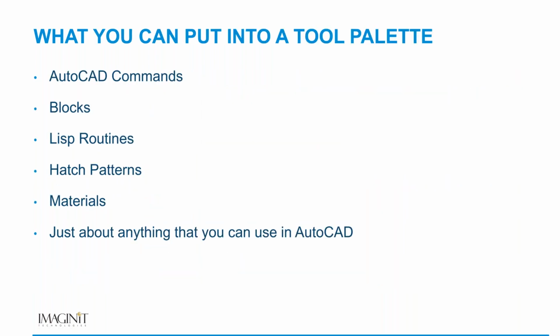So what can you put into a tool palette? Well, pretty much anything. You can put AutoCAD commands, you can put blocks, and you're not actually putting a block in there, you're putting a pointer to a block. So it's a quick way of holding on to your standards and or common things you use most often. You can put Lisp routines in there. In other words, if you have customized Lisp routines, you can put those commands in there. You can put hatch patterns, materials, and just about anything you can use in AutoCAD, you can put in there.